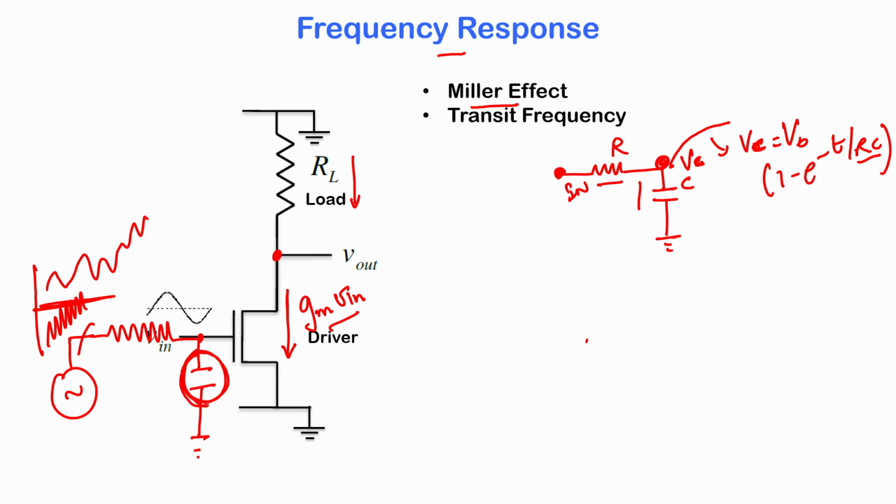The way you define this capacitance is to see what are the elements the transistor is driving. So, on the face of it, this capacitance is basically your gate to source capacitance of the MOSFET. There is a channel here and there is a gate to source capacitance in the MOSFET. Okay, so, that is not the problem, that capacitance is there in any case. Now, the problem arises because of the gate drain overlap.